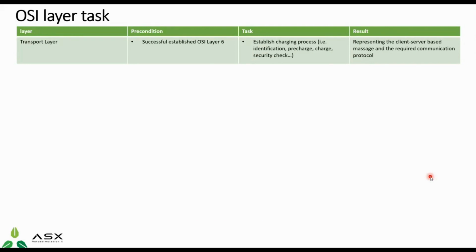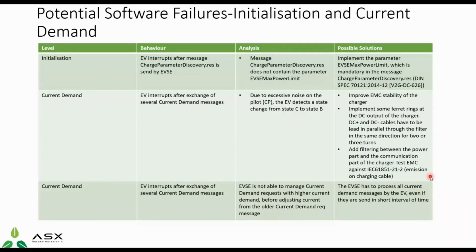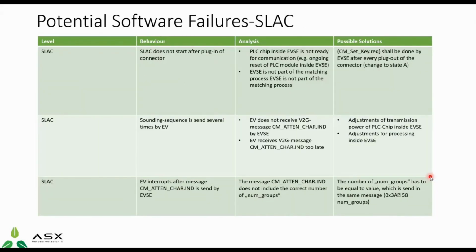But why... there are some software failures in CCS2 charging while we are working with CCS2. First is for the SLAC. Many times we have seen the SLAC does not start after plugging in the connector.